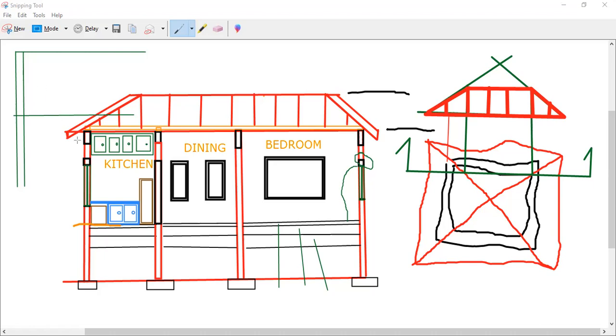Let me repeat. To draw the vertical walls and get these distances across nice and smooth, quick and easy, let me delete this one. You establish a first wall here, right? You're now going to offset this wall, as these are all parallel, to a distance equivalent to the wall thickness. In this case, typically it's 150. But the question states that it has plaster on both sides. The external walls should be 150 plus plaster, while the internal walls should be 100 millimeters. So you would offset this to 170.